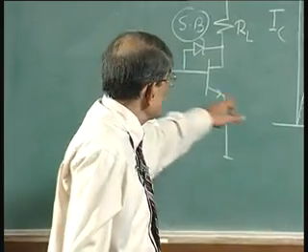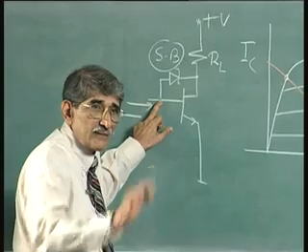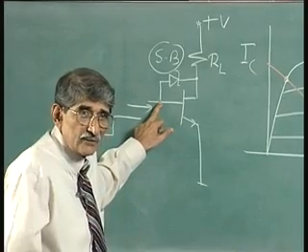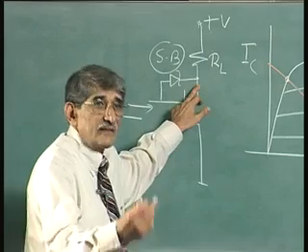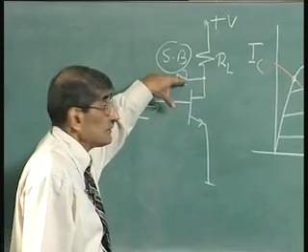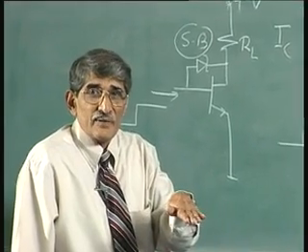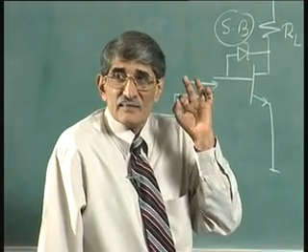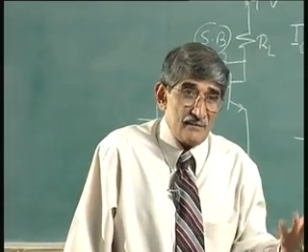So, you get an ohmic contact here, p type region, and the metal on the p type becomes ohmic, because of the low barrier height, because of the Fermi level pinning. Metal on the collector N region becomes rectifying very easily. So, without showing the diagram, you can feel that this is a single device with just a metal layer put between the collector and the base. So, that is the technology that is done there. This is the TTL, Schottky TTL, STTL.